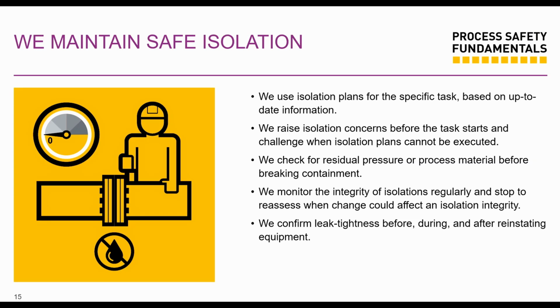Or it could be a hydrocarbon line. And a lot of old systems don't have double block and bleeds in place, and you only use a single valve that could be passing. You use that single valve as your isolation, and it could be passing. And you have hydrocarbon in the line, and that sprays everyone, and you have an ignition. Or it could be H2S gas, gets everywhere, high ppm, you know. So those are a couple of examples.